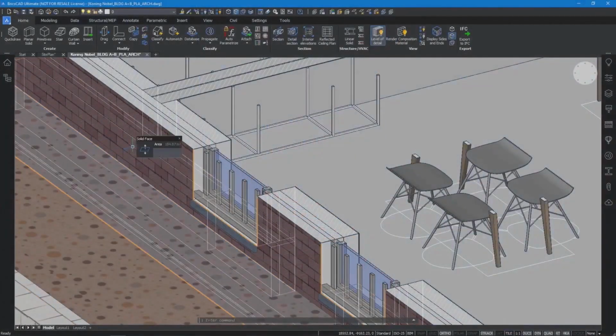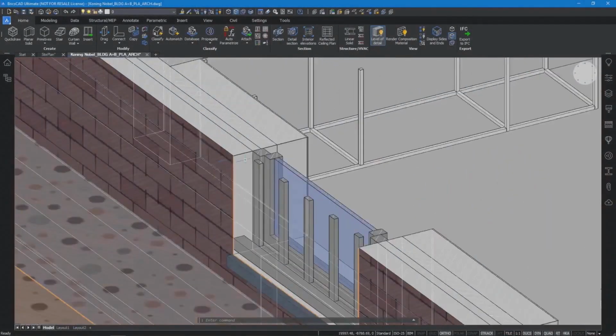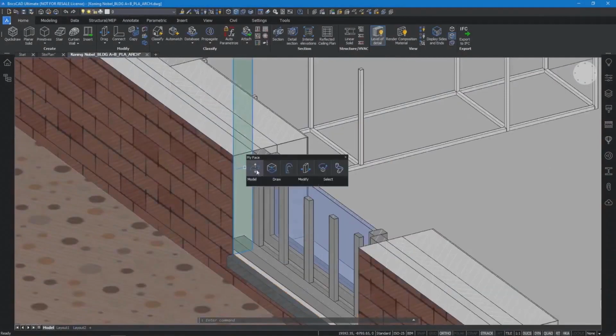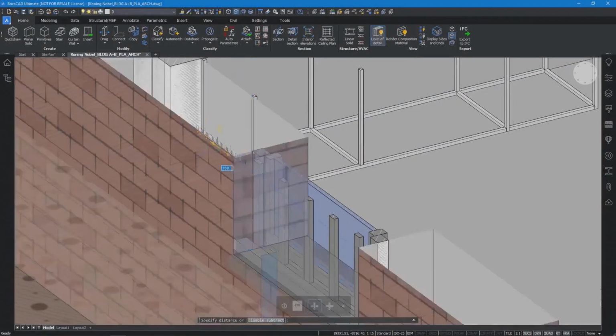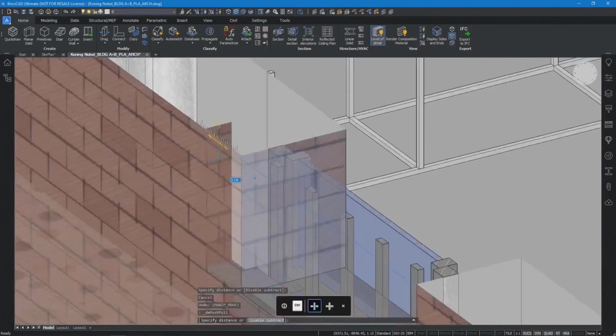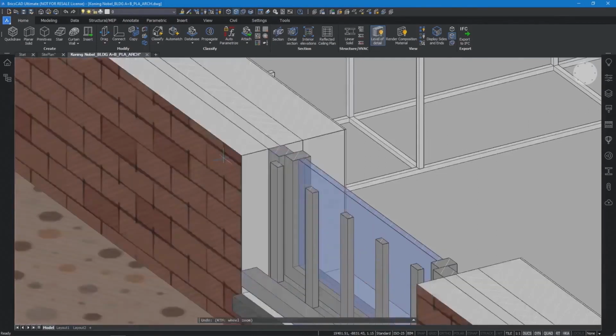Okay, now that the level of detail is on, I will show what that actually means. It means you can take your plies and edit them, which is handy when you want to increase the level of detail of your model. Keep in mind, once again, that your level of detail setting for the render composition materials makes a difference when you take your model to Twinmotion. If the level of detail is on, it probably is going to be a heavier model in Twinmotion, since they're going to be imported as separate solids.